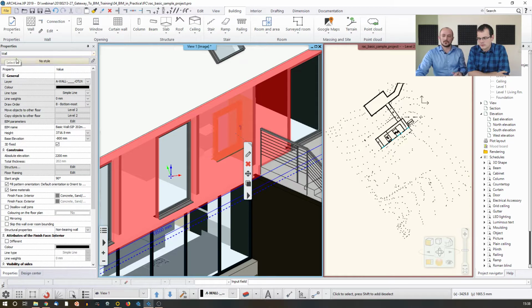This is actually a wall. So what's the deal here? In some situations, like in this specific situation, the wall was modified in the original software in a way which cannot be directly converted without losing the original shape. So in this situation, the software decides to keep the shape and allows you to decide whether you would like to keep the shape or you prefer editability. And this goes with this option.